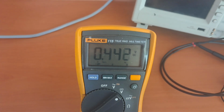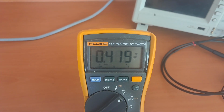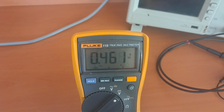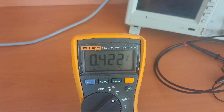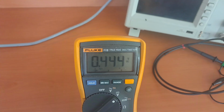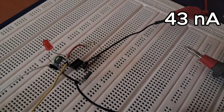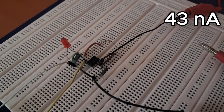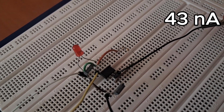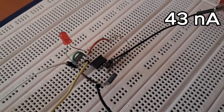I'm waiting for it to be stable. It's around 0.44, and I'm gonna divide it by the resistance. I calculated the result as around 43 nanoamperes, which is a lot bigger than the daylight one, which makes sense since more electrons were emitted on the photodiode because there was more light.